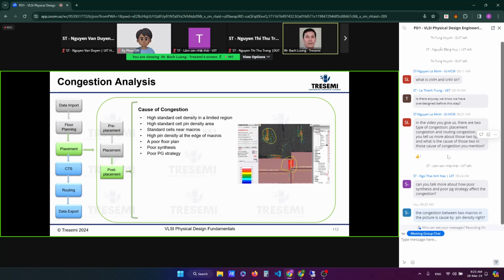So if your design is designed to run at 400 megahertz, that's your target at every stage of the design, right? In synthesis, the standard flow is wire load based. It doesn't have any global routes or any placement, so it's based on the number of cells and loading by wire load.